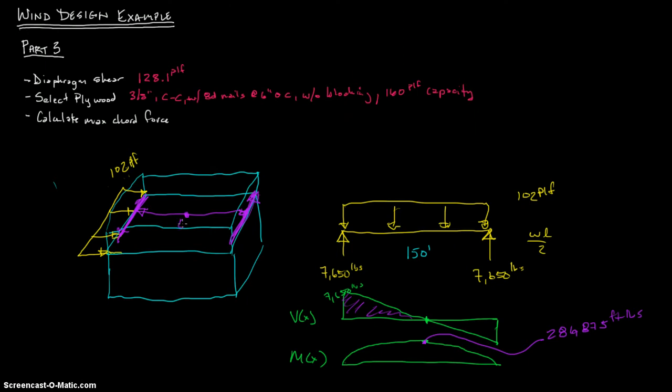And what is this? This is 60 foot from here to here. So all you have to do is take this and divide it by 2. If you remember the moment, so if we're looking at it's at the halfway point. If we looked at this in a moment diagram and put it on here, the moment diagram would look like, it's hard to show, but it would look like that. So we know the moment, this is 0, this is 0, this is max right here in the center, and that's the 286,875. So we're like, oh, okay.